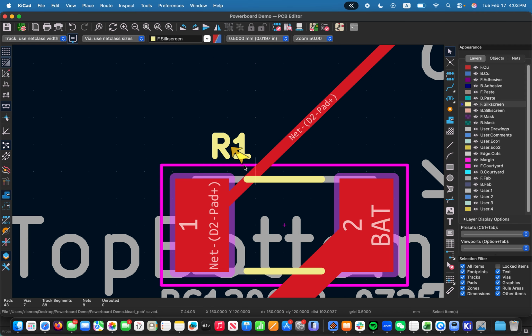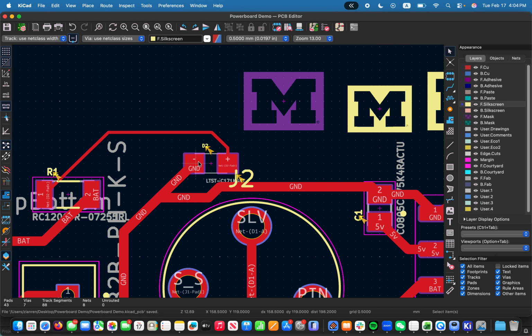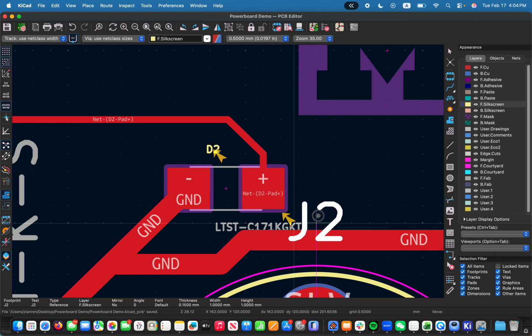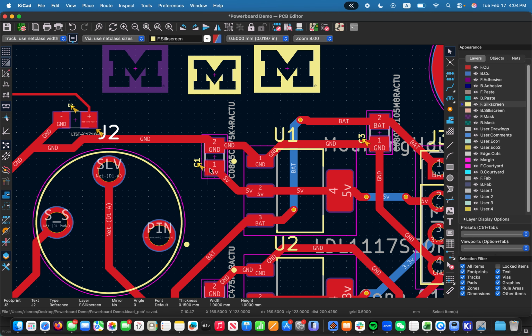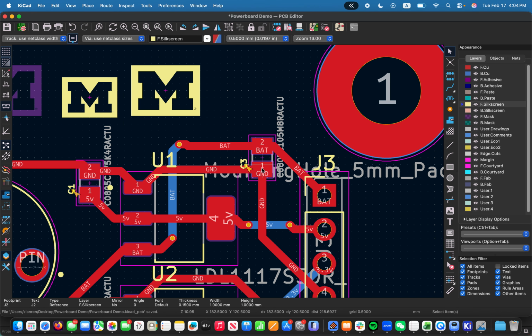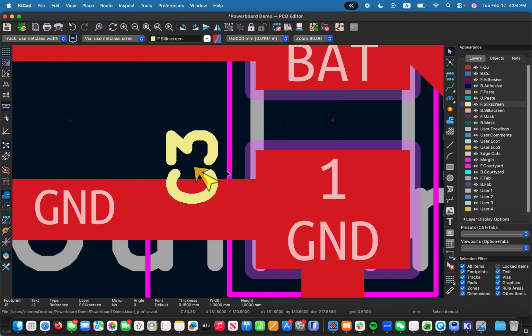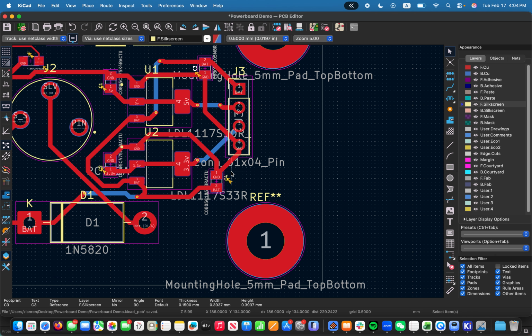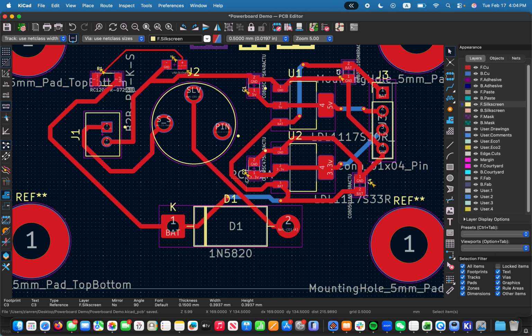And see, it actually points to where those warnings are, and you can see these are just text warnings. So this J2, we can just move it a tiny bit. This C1, I think it's basically saying it's too close, but that's okay. C3 here saying that this is too close, so let's move it a little bit. These are just mostly for aesthetic purposes.